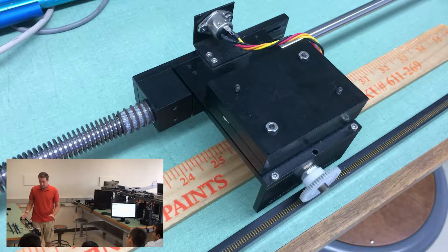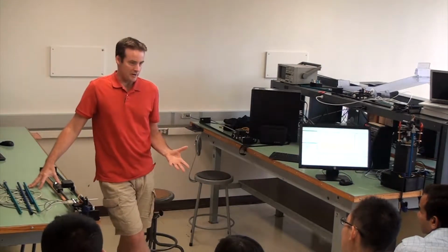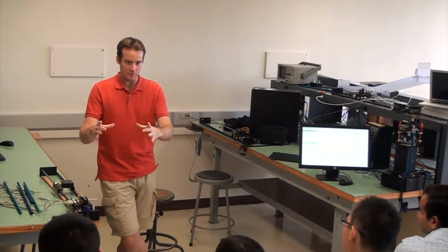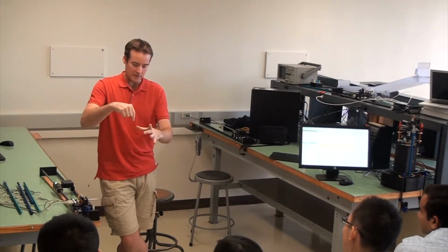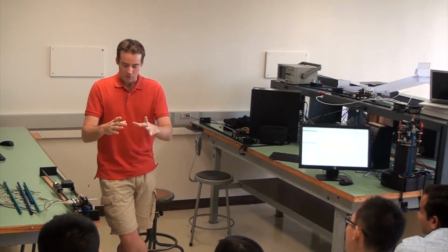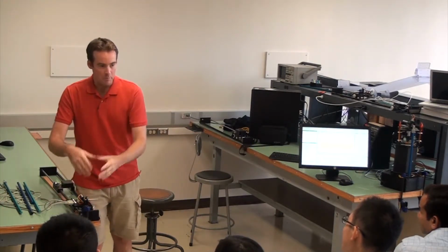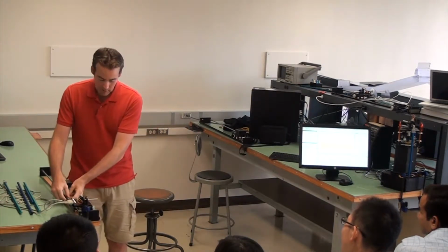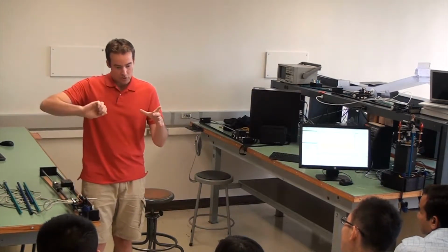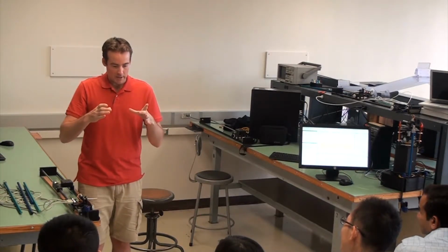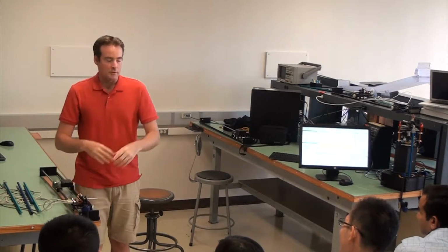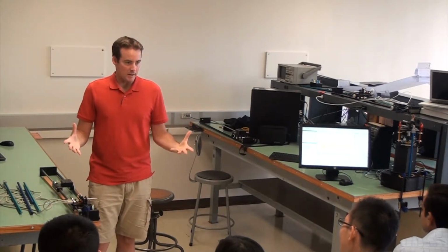Suppose now, this is kind of like a 3D printer. You think of a 3D printer, there's a stage that has to move around. You guys have seen 3D printers before? So there's a little stage and there's a nozzle with the hot spigot that shoots out plastic, right? And that stage is driven by some motor, and then there's some sort of rubber belt that can move the platform around. That's modeled by this spring here. If you crank the motor over, the platform is not going to perfectly move over instantly. It's probably going to wiggle a little bit. The spring serves the same purpose of modeling that wiggling behavior.